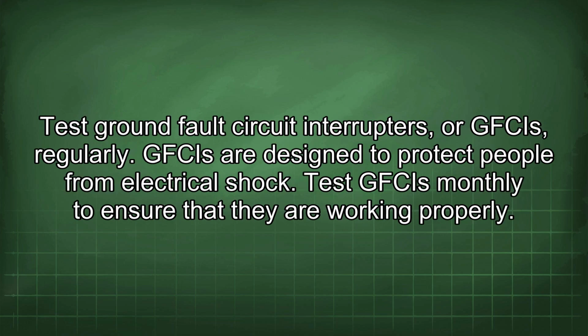Test ground fault circuit interrupters, or GFCIs, regularly. GFCIs are designed to protect people from electrical shock. Test GFCIs monthly to ensure that they are working properly.